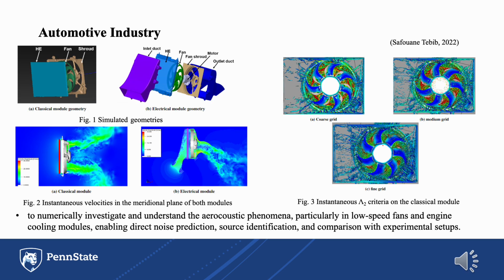So here is another example in the automotive industry. This group used LBM solutions to investigate the aeroacoustic phenomena, particularly in low-speed fans and engine cooling modules, enabling direct noise prediction, source identification, and comparison with the experimental setup.